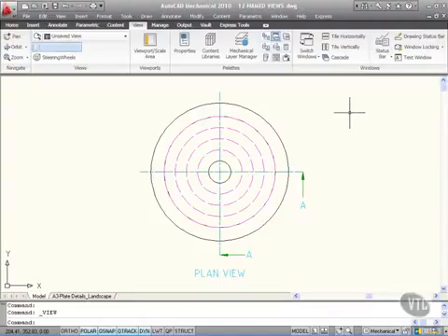Another more traditional way of setting up scaled viewports in your AutoCAD Mechanical, in your Layout tab, is to utilize named views. Now, we have touched on these a little bit before already during this particular title, but we're going to go through it again to recap and go into it in a little bit more detail. So, I need a named view now of my plan view.